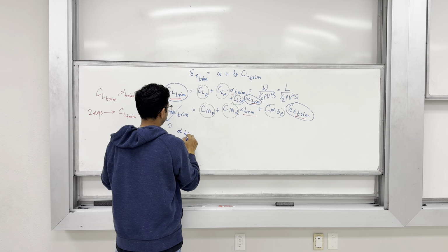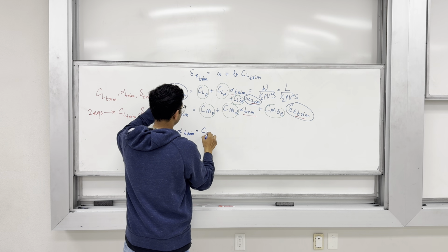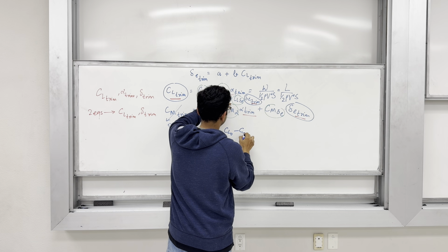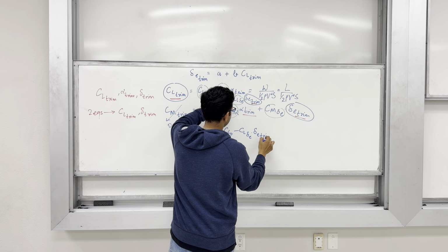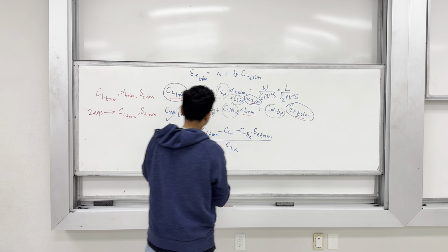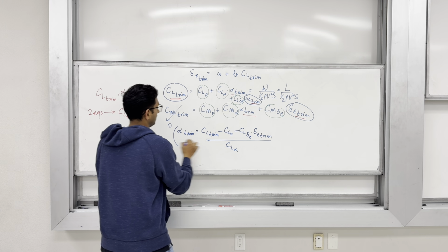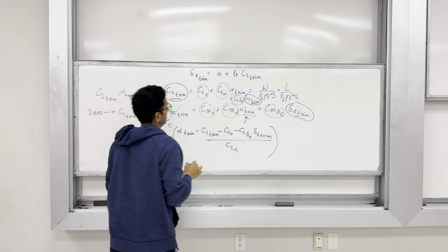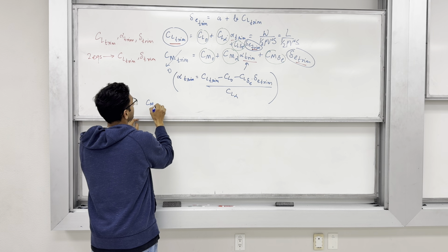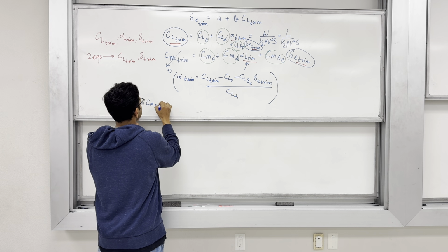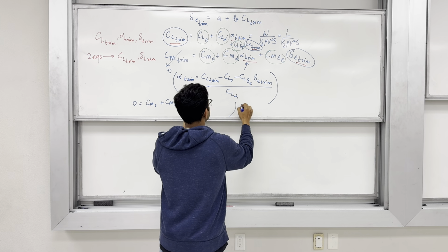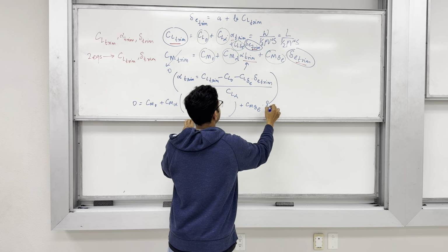So, I will say alpha trim equals CL trim minus CL naught minus CL delta E times delta E trim, divided by CL alpha, and then I go ahead and plug this in here, which would give me CM naught equals 0 plus CM alpha times this thing here plus CM delta E times delta E trim.